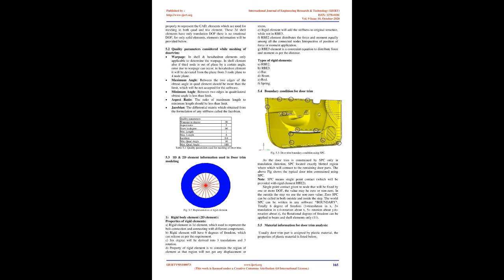The modal characteristics, stiffness, strength, and anti-extrusion of a newly developed passenger vehicle door assembly were calculated and evaluated by several finite element analysis software packages. The structural problems were discovered by finite element analysis and were modified, finally achieving the expected door structure performance target of this new vehicle. The issue in focus is to predict the performance of the door assembly using powerful finite element analysis software and optimize the structure to meet the design targets. It is observed that this method has been used to forecast the performance of the vehicle door efficiently when it was designed.